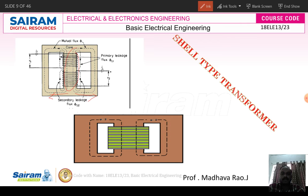In this type of transformer, the core is surrounded by the winding. Previously, in the core type transformer, the winding is surrounded by the core. In the shell type transformer, the core is surrounded by the winding. And next, in this type of transformer, near to the core we need to place the low voltage winding, and in between the low voltage winding we need to place the high voltage winding. Why is it so? To reduce insulation cost.